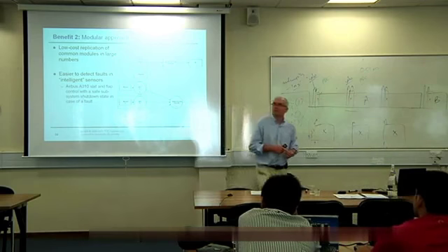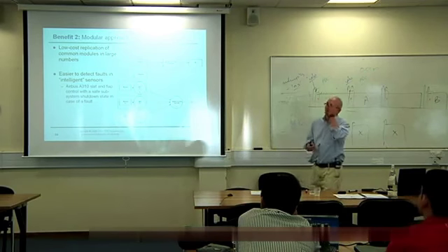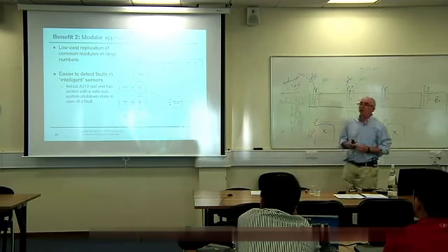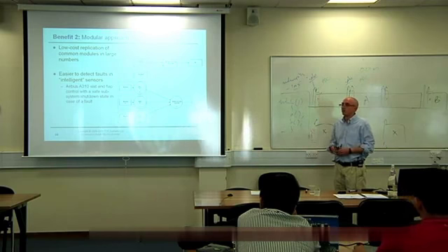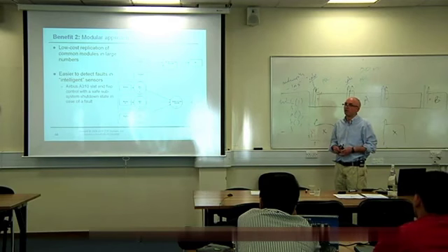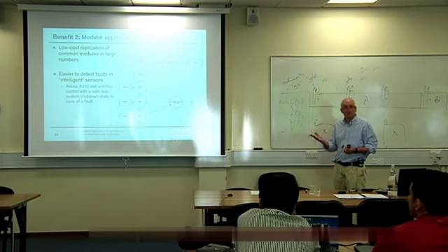Do you want to reset them and then link back to normal, so using another method? I want to get the plane on the ground without killing anybody. Give control back to the pilot, so can he still control? He can't. He has no control over the rear part of the plane. So what do we want those rear control surfaces to do? Something they can't. You can't control them, but what's the best fail-silent position for the rudder on the aircraft?